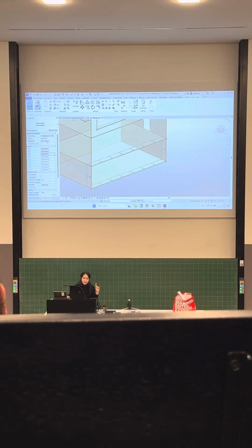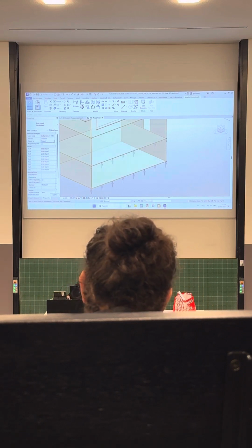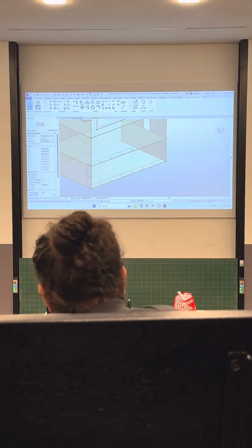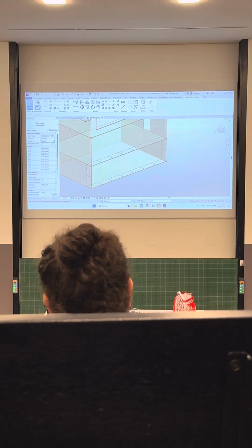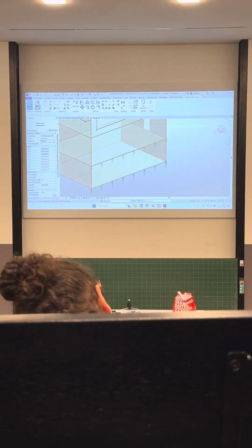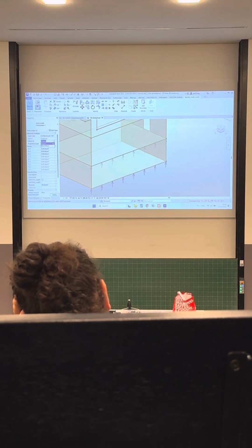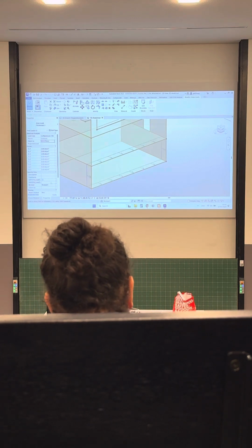This happens because we are orienting it to work plane. We can orient it to project. It will be here. So now you can see the difference between the work plane and the project. Because this is the Z dimension of our work plane. But in the project, as you remember, Z is a vertical one. So if we put the project and Z, it's going to be in this coordinate. So it depends on you which coordinate you would like to use.